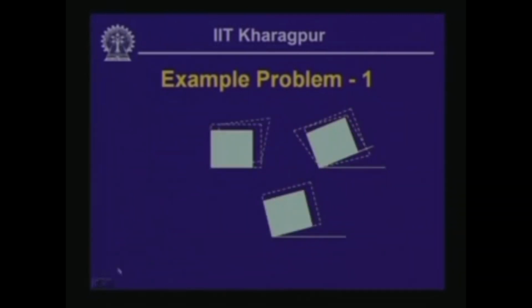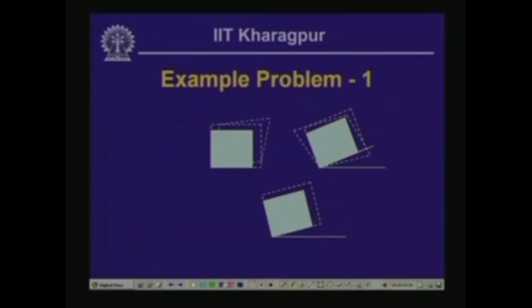Now, once this particular element undergoes strains, this is the configuration which we expect. In the initial stage, we had epsilon x as 340, epsilon y as 110, and we had positive shear, which is denoted by this as 180, and this is the orientation of the element in the initial state.